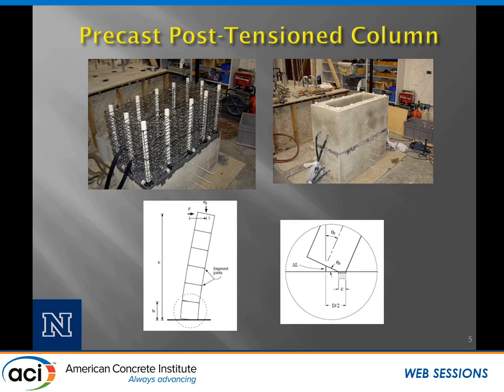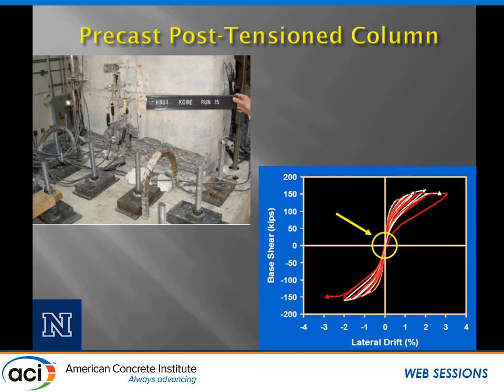So one of the first tests that I was involved in was a segmental project where we were looking at post-tensioning this system together. It was just a series of blocks that were stacked on top of each other. This is the actual test specimens up here on the top. And one of the things I wanted to point out with this particular experiment was that there was no reinforcement crossing this bottom joint. So this truly was an only post-tension system. When we look at this system, it actually performed extremely well. You can see that even at large displacements, we had no residual displacement on the system. This was a shake table test that we did at our facility here at the University of Nevada, Reno.